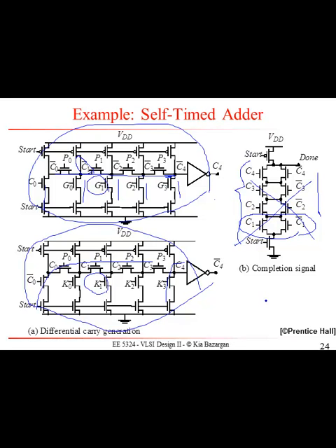And here, of course, I'm assuming that you're using this logic and the next pipeline register is going to fetch all the S values or all the intermediate C values in computation. If the only output that you have is going to be C4, yes, then you can do that. You can only take C4 and use that as the done signal.